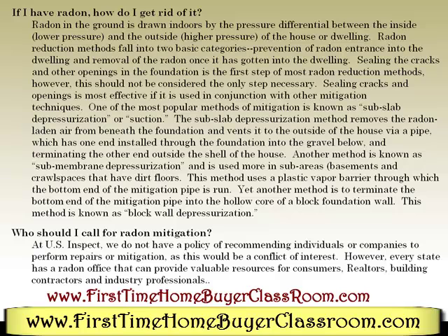Sealing the cracks and other openings in the foundation is the first step of most radon reduction methods. However, this should not be considered the only step necessary. Sealing cracks and openings is most effective if it is used in conjunction with other mitigation techniques.